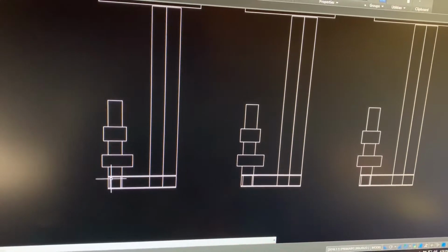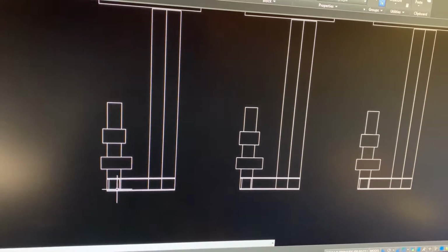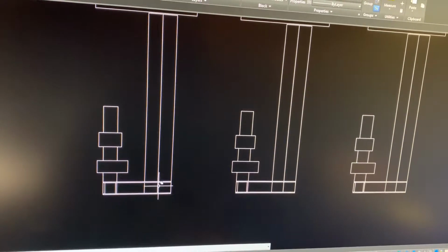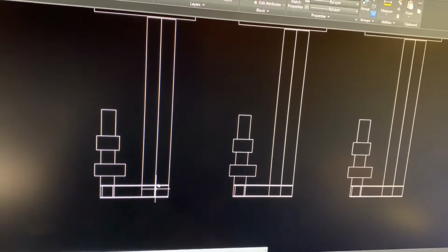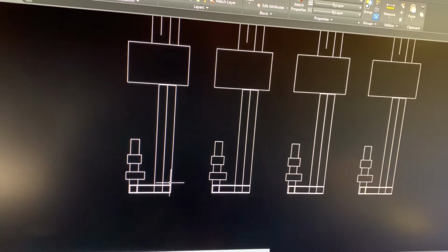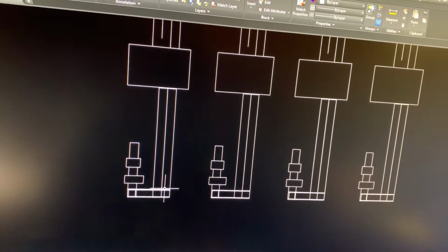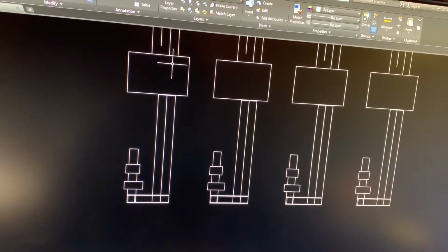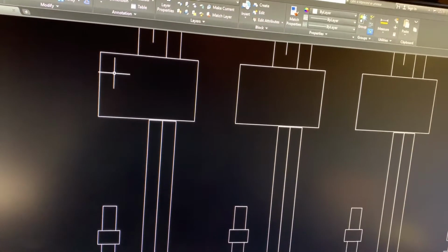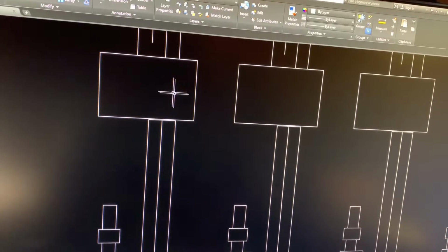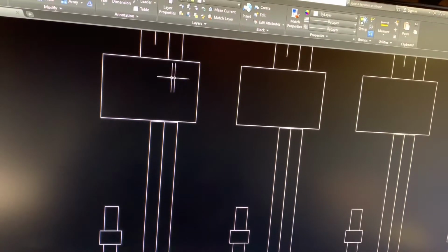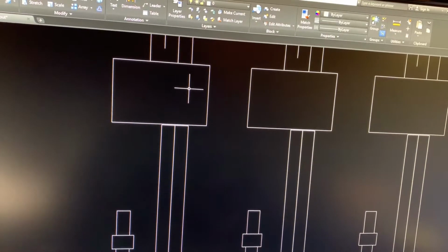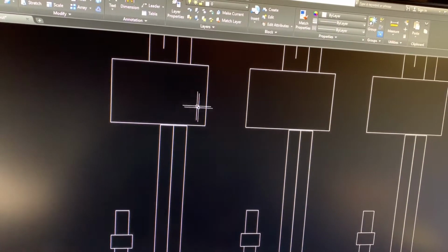Then it'll be pushed out to here, and an overhead gantry will pick up the sand casting and move it over here to whatever spot is open on this conveyor here. This automated conveyor will move the sand casting over here, and it actually goes all the way through. So in here, we'll have the molten metal being poured into these sand castings automatically. There'll be a laser switch to tell when the molten material is to the top of the casting.